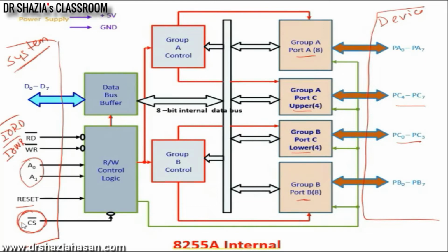As we have seen in your previous class, you have a latch or a buffer. That latch gets enabled under which situation? Only when there is an INTA bar signal and for a specific address only should this particular buffer or latch get enabled. I am communicating with a device which is connected to port A. That means the microprocessor has generated that address.